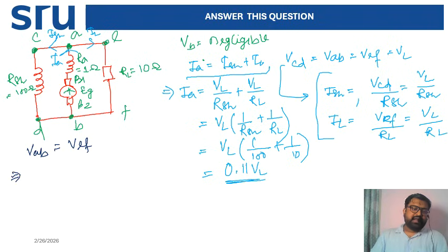Now we can derive the armature equation, as VB is negligible. I am just neglecting the VB term, right? Then armature voltage drop, how to find out? That is the generated EMF minus IA into RA, right?